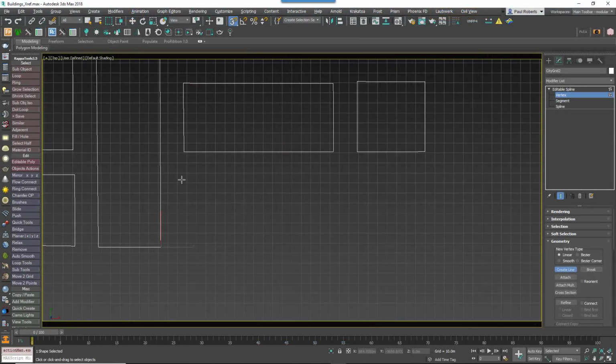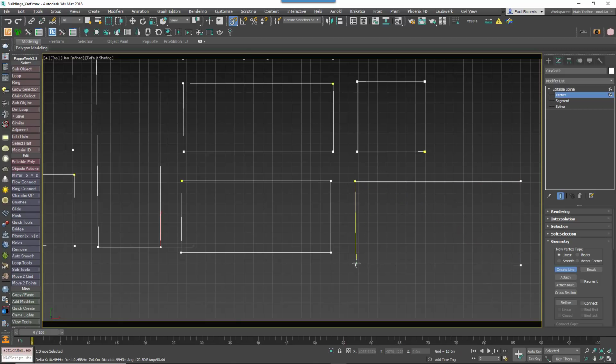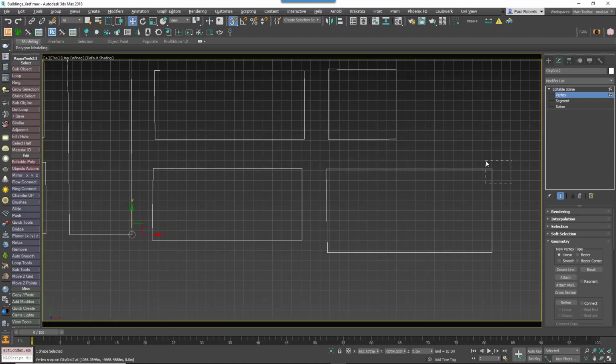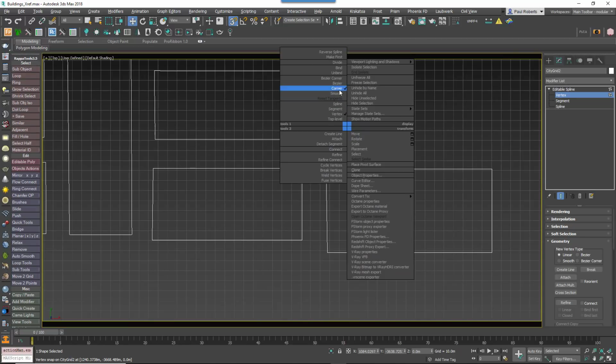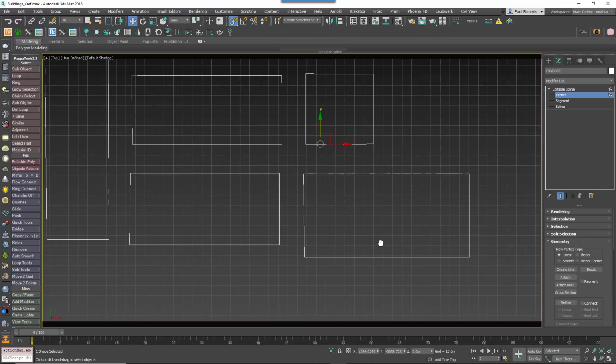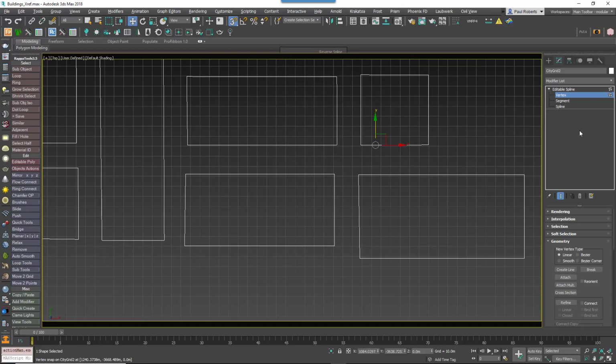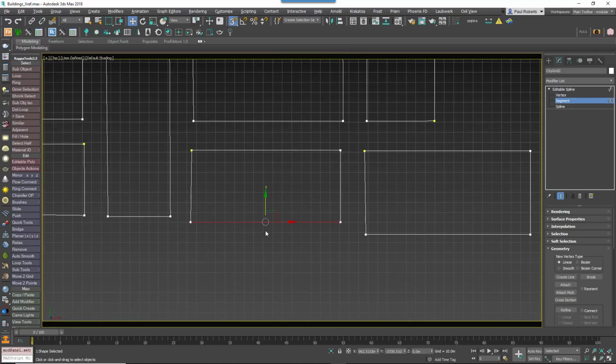So get started by laying out the city using 3ds Max's built-in tools to create a closed spline for each city block. When designing the city, there are a couple of things to consider. Firstly, the techniques in this tutorial work best with rectilinear city blocks. Secondly, vertex type should be set to corner for 90-degree bends. These will be used by RailClone to add corner geometry, but they're also useful to add zebra crossings and other details at the intersection of the streets.